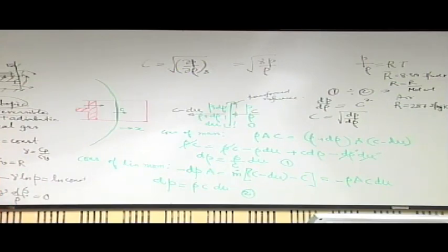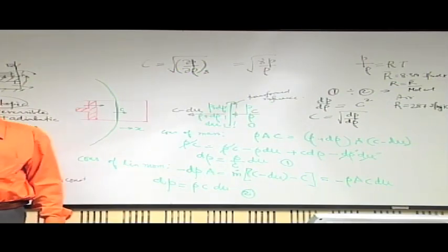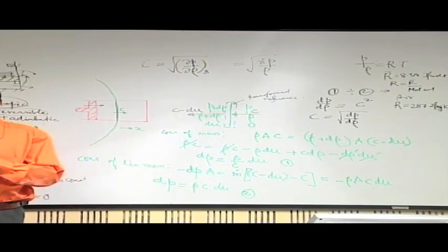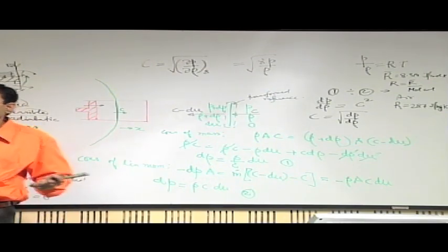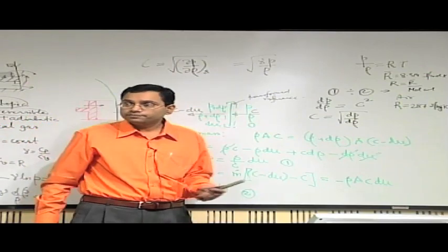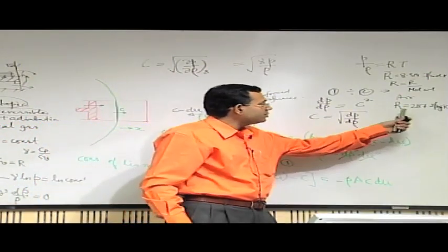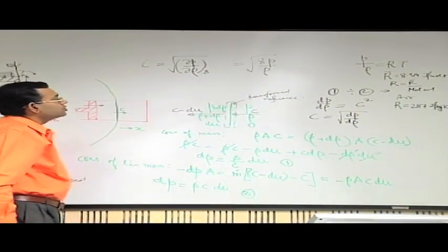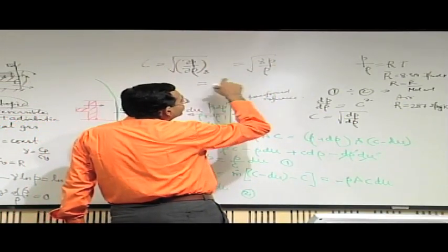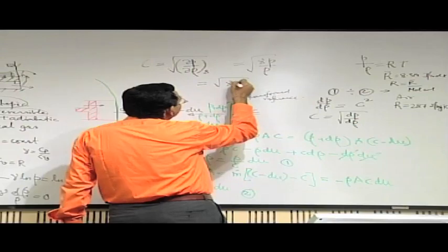Of course the molecular weight of air is not a very simple calculation, but you may roughly consider it as some proportion of nitrogen and oxygen, like 79:21 roughly, and then calculate the equivalent average molecular weight. If you do that, this will be the value of R. So keeping that in mind, we may replace P by rho as RT, so this becomes root over gamma RT.